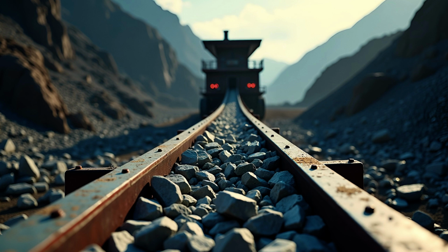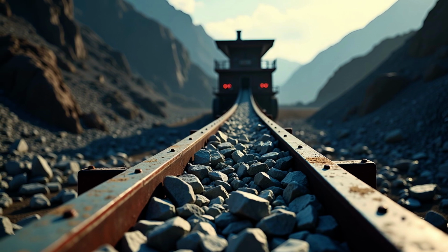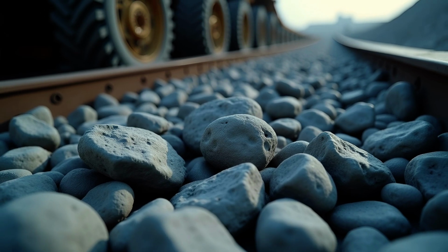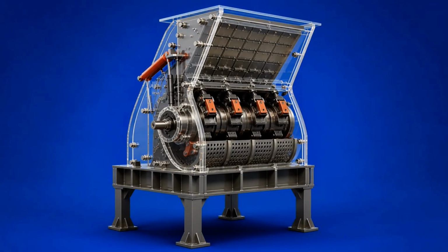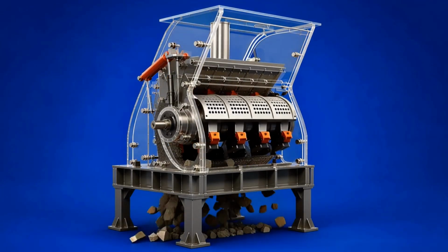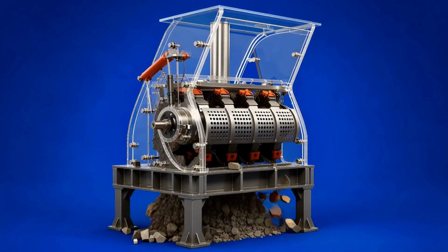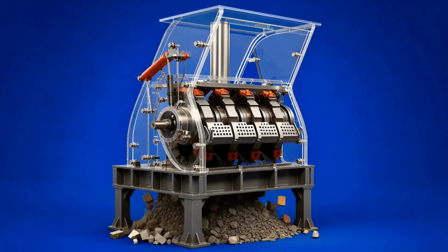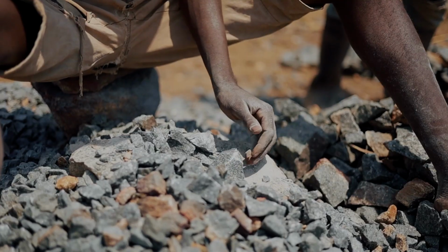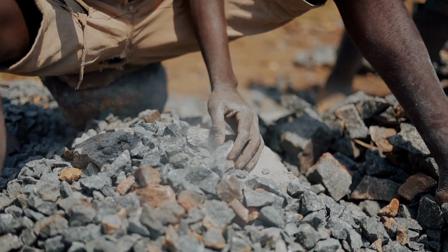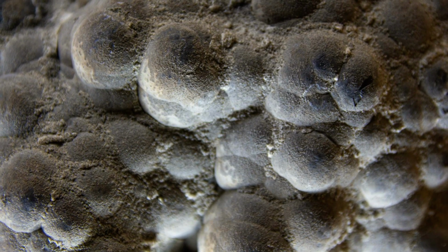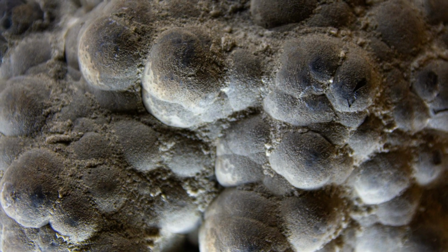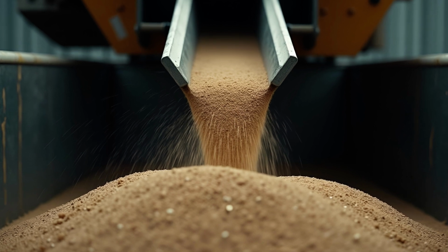of mineral particles. After primary crushing, the material is still too coarse for efficient separation, so it proceeds to a hammer crusher. Unlike the jaw crusher, which uses compression, the hammer crusher uses impact energy. High-speed rotating hammers strike the material repeatedly, breaking it down further. This reduces the particle size to below about 12 millimeters, or roughly half an inch. At this stage, a much larger surface area of the mineral is exposed, improving the efficiency of downstream processes.